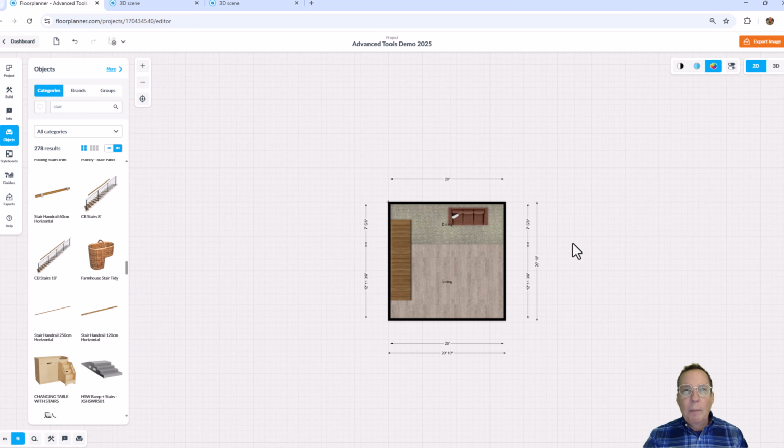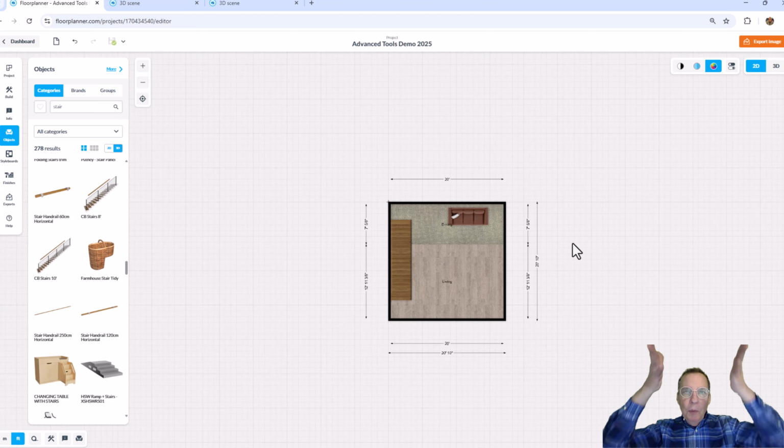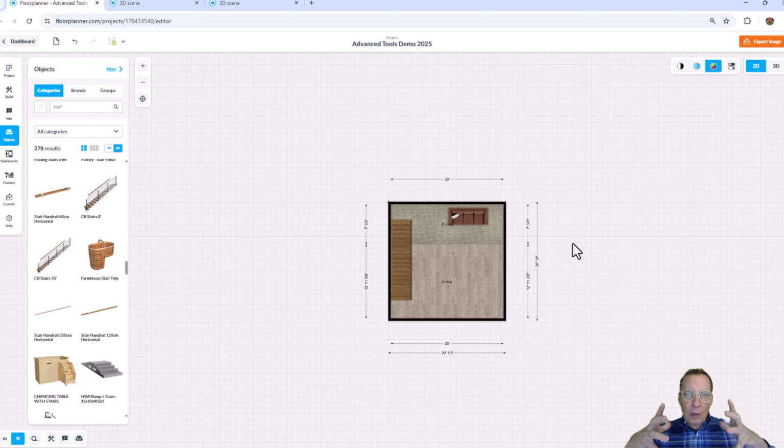Now here's the trick. Again, build your first floor, your ground floor, your basement first, and then duplicate that floor with all of its essence to be your second floor next. If you do that, they'll be directly above and below each other. So your first floor would have contained your structural load-bearing columns or load-bearing walls, which realistically are above and below each other for the loads to be transferred through your building.